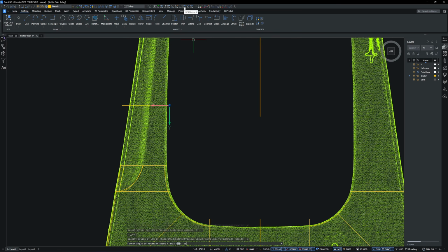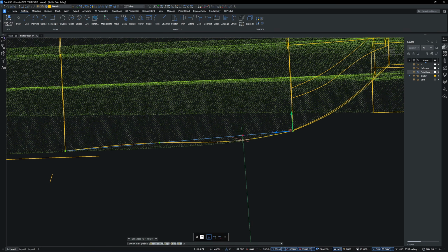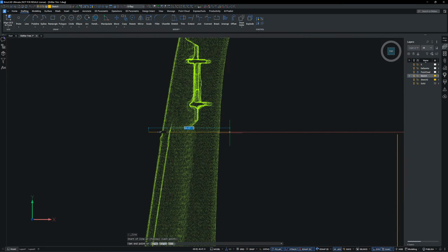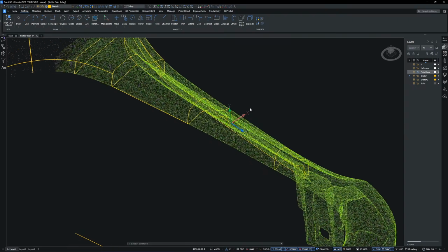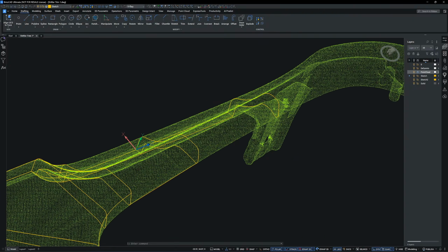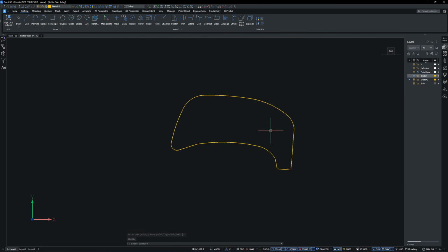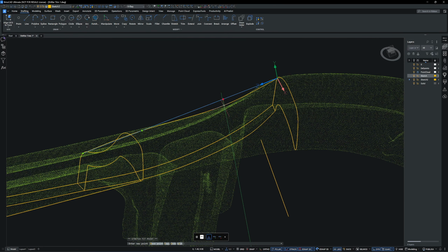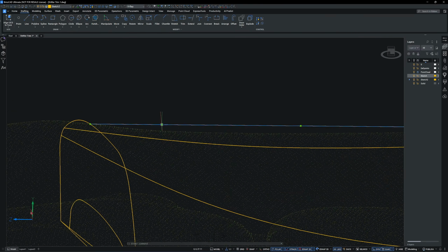Most car trims are modeled using the Loft command. Technically, Loft constructs the model by surface patching with sketch boundaries, but it creates watertight surfaces much faster than using the surface patch command with the profiles and rails. The only shape you can't create with a loft is a dry junction. That one requires surface patching to model.